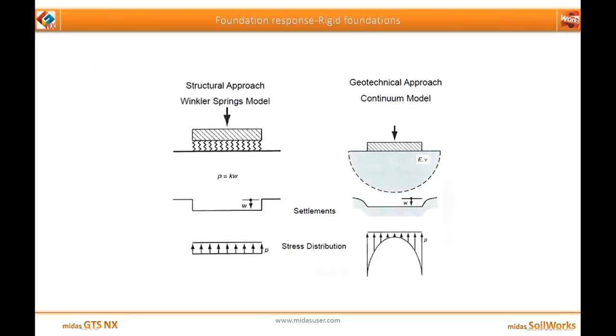So as you can see, whenever we go for rigid foundation in the structural approach, the stress distribution always comes as uniform from below, and the settlement is also considered as uniform. When compared to the real ground situation which we obtain in the continuum model, the stress distribution is very much different from what we actually have in our structural model.